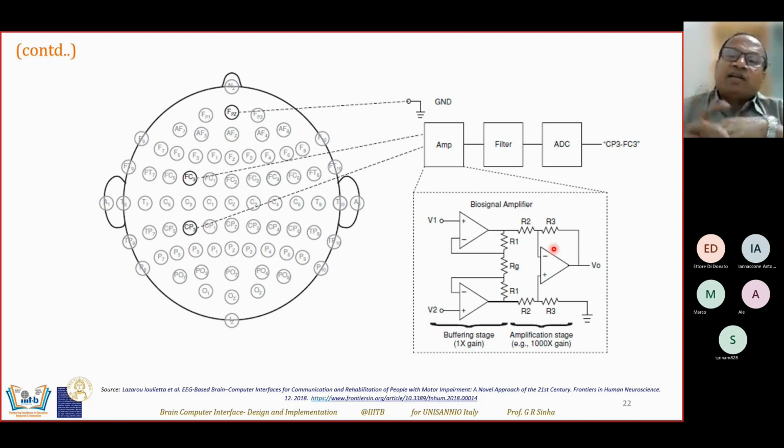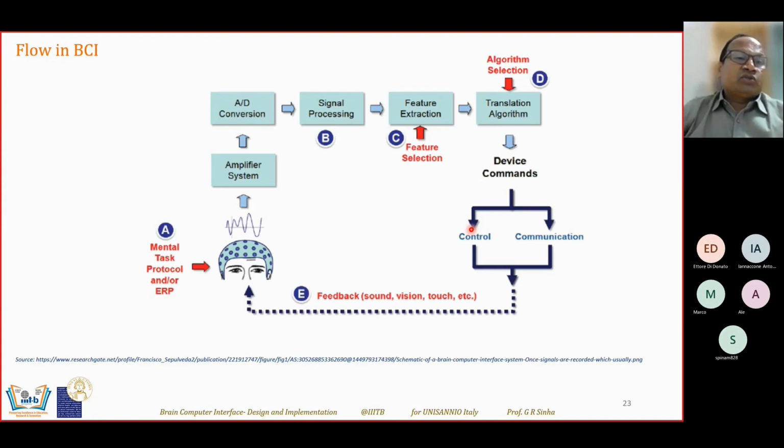Buffering stage, you can definitely answer why a buffer is needed, because you can never give input directly to the amplifier. So the signal will be stored for some time. Probably the amplifier is working with the previous data. So for that, it will always be waiting here in the buffer stage. So buffers are also used for impedance matching so that there is no overload in the output. For that, a buffer is always the device which is used.